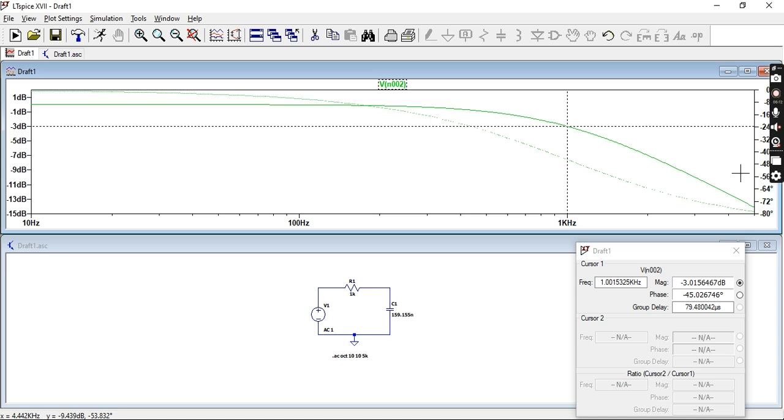You'd set up an AC analysis, you'd inject an AC signal, then you'd run your simulation based on your frequency range. So just make sure that your frequency is set up accordingly. If you had higher frequencies, obviously you wouldn't have stopped at 5 kilohertz, it would have been higher. So just look out for that. So this is my simple example of an AC analysis.